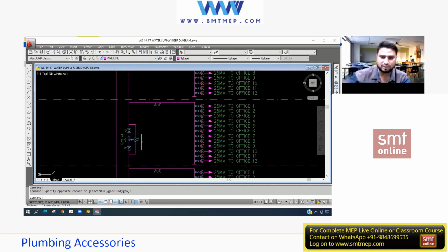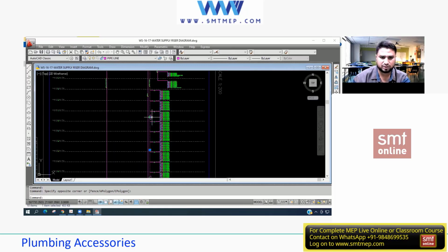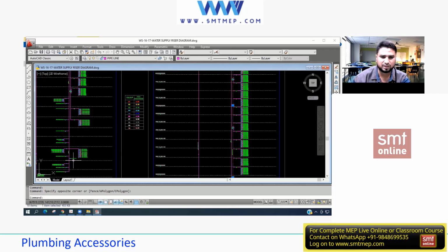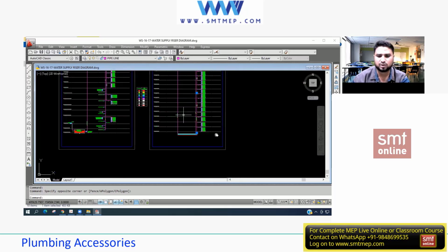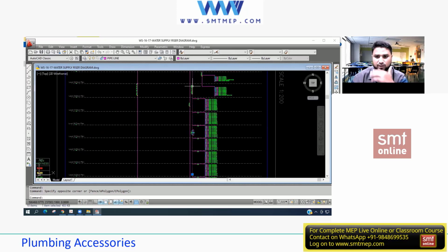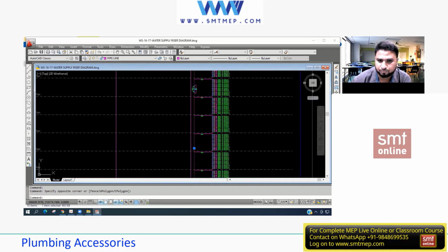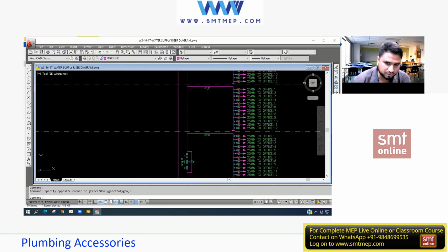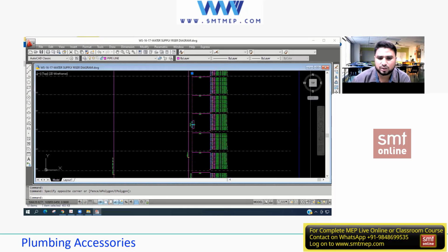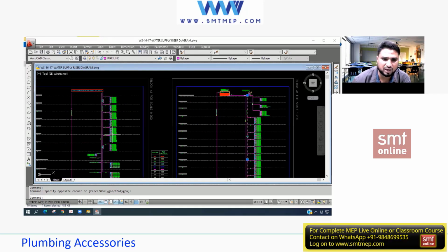The more it's coming down, it increases more and more. So what do people think? For example, this 30-floor building, if I'm supplying till this floor, like ground floor or first floor, what do people think? Will the pressure be 60 psi or 80 psi or more than that? Very huge, isn't it? More than that, right? So you can see there are n number of PRVs. Okay, here, Umair, follow, your doubt will be clarified over here. Okay, so there's one more PRV over here. And further, one more PRV.